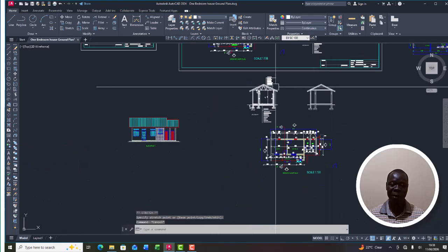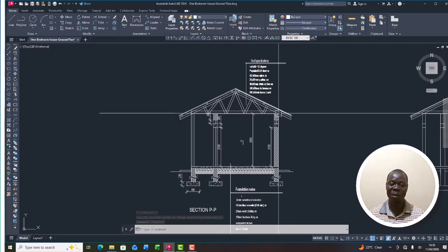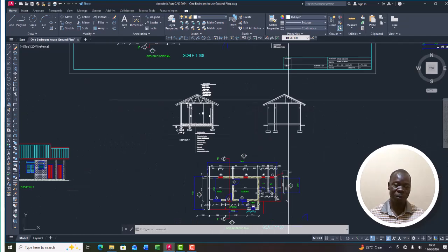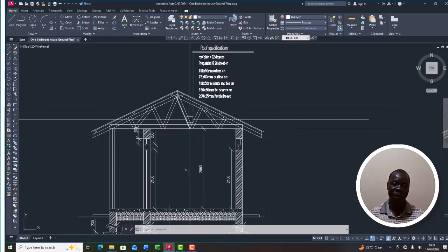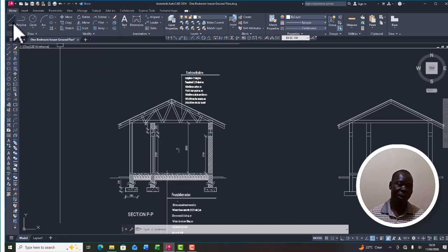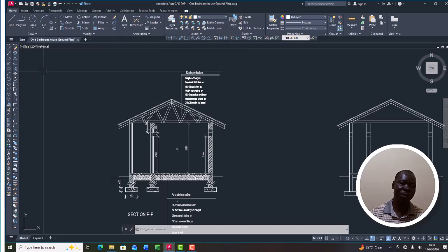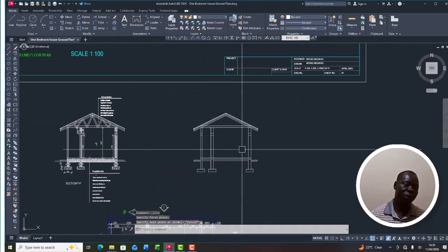So far, when you look at our thing, it's now coming up. So how do we draw these struts? So the struts can make it at the angle of 60. So you pick this line. Let me use construction line. So I type XL, enter.